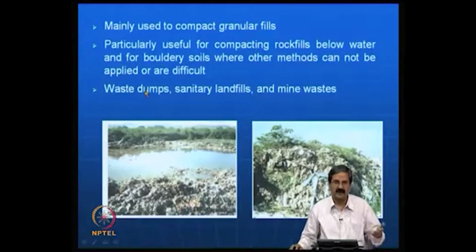Suppose you want to recover some areas for rehabilitation, say for example construction of multi-storied buildings in the outskirts of a city. In the outskirts of the city you always have waste dumps and, of course, sanitary landfills. Waste dumps are quite common, and if they understand that a waste dump is going to be very dangerous, then they convert it into a sanitary landfill. So in either case, waste dumps and sanitary landfills are very good candidates for dynamic compaction,